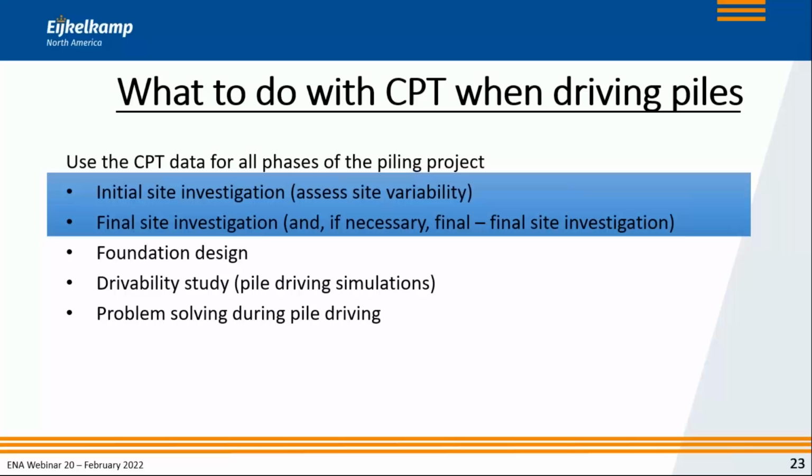Then you do the planning of the execution phase, and then go on with the problem solving or the monitoring during the pile driving itself. Because only once the pile is in the ground, and you're sure that it is in the ground without any damage, is your pile driving project complete.